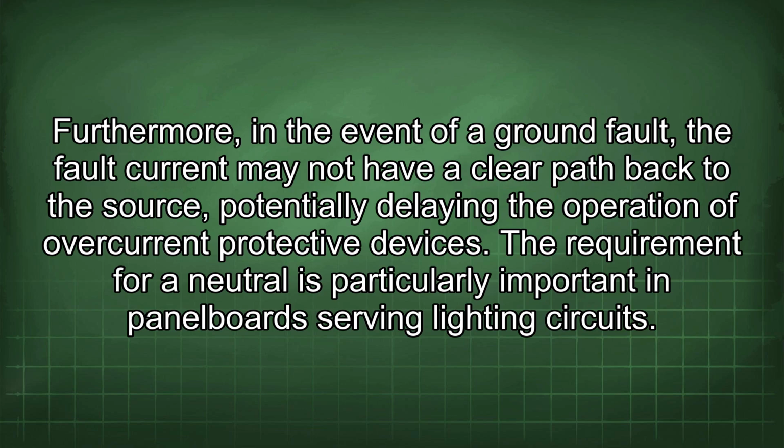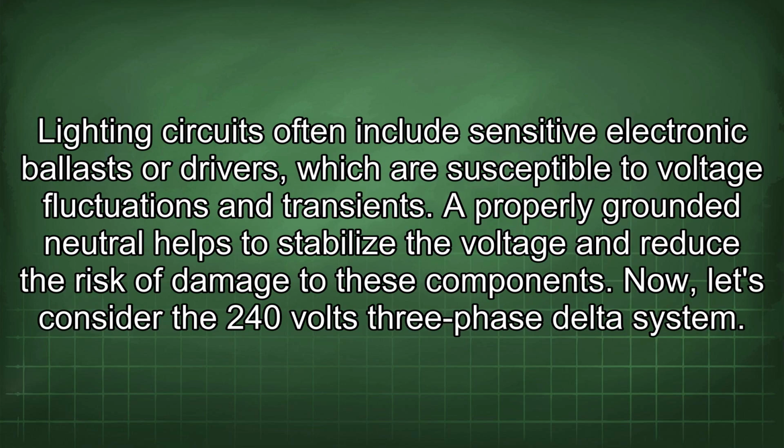The requirement for a neutral is particularly important in panel boards serving lighting circuits. Lighting circuits often include sensitive electronic ballasts or drivers, which are susceptible to voltage fluctuations and transients. A properly grounded neutral helps to stabilize the voltage and reduce the risk of damage to these components.